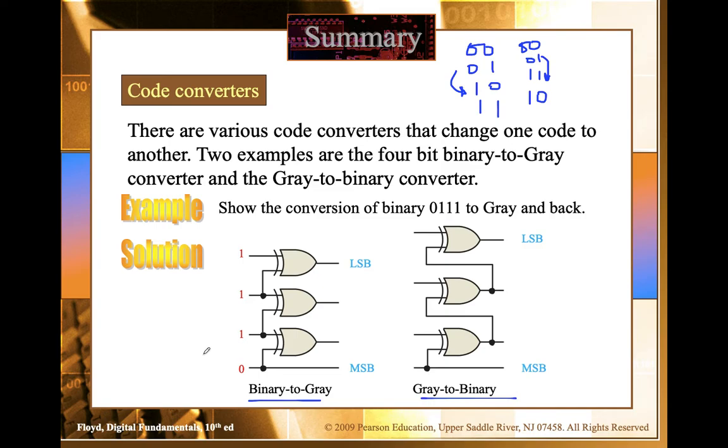It is being shown that we can use this particular combination of XOR gates, where, in an XOR gate, if the two inputs are different, the output will be high, right? So 0 and 1 are being XORed, and what you receive here is a 1. This 0 will be propagated just like that. Again, 1 is going here, 1 is receiving here, XOR gate 1 1 gives 0, because we know that if the inputs are the same, the output is 0. Again, inputs are the same here, output will be 0.